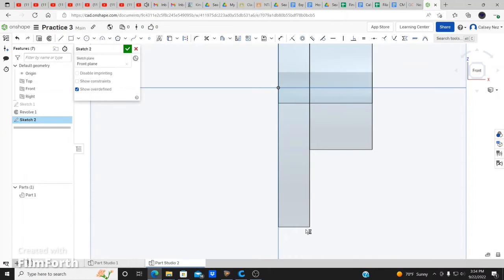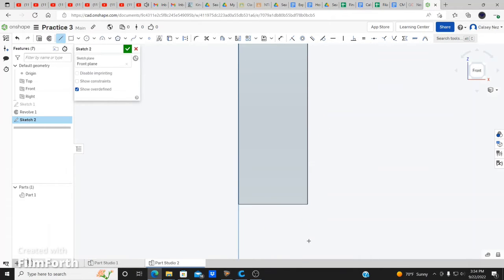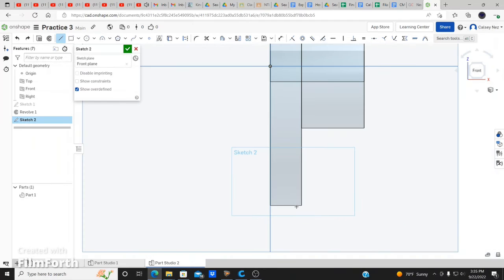Okay, once you got this translucent and we have the front view already set up, what I'm gonna do is over here, I'm gonna add in my triangle. So I'm gonna add in a triangle right in the middle right here. Let's see here. Our point for the first one is gonna be right here on that line. Oops, this doesn't give me the line. This one's gonna be tricky on Onshape most of the time because it's very hard to get that exact point on here because we actually added in our new feature.